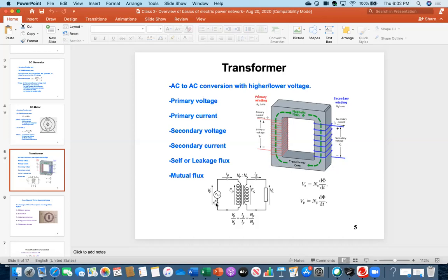And then you see here the equivalent circuit of this one. Like you applied a voltage Vp here, current is flowing, which is Ip. This is the primary set of coils. These two symbols represent the core material, the core. This means in between there is only air, there is nothing. And then this is the secondary coil, secondary voltage, secondary current. This symbol represents the load. This means if you connect any load, then the current will flow.